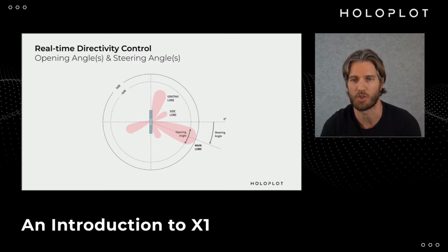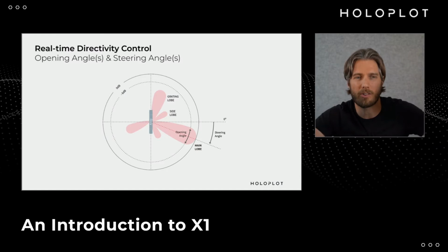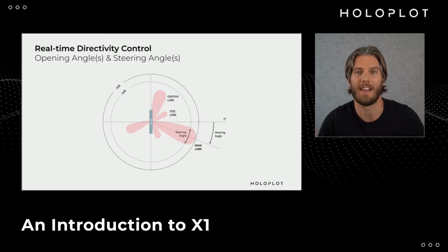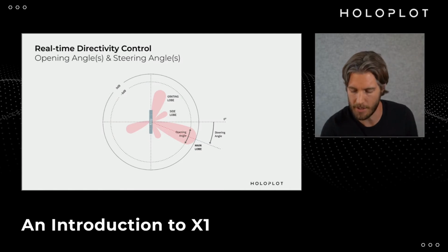So we're able to spread that and spread the phase response. And then to mitigate the impact of the side lobes, we deploy side lobe suppression algorithms in the form of gain tapering around the edge of the box. So, reducing the level in the drivers to the outside of the box, which again reduces the level of the side lobes that are created when you're steering the beams.